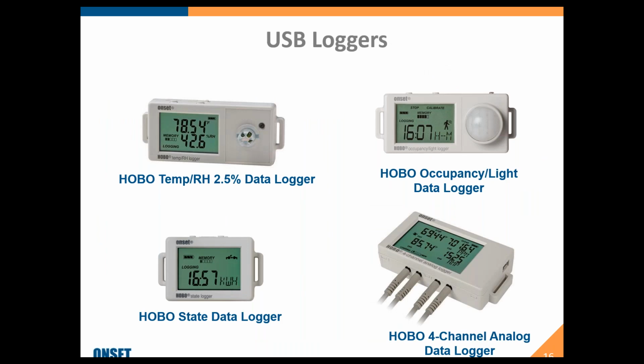So just be aware of that, and we'll go over a few of those. The different types of loggers that we have, I'll start with the USB. So temperature, relative humidity, occupancy, light, on-off state, like I was saying, that may be an open and door close, or an external channel on our UX90 state logger that will take in kilowatt hours, a pulse from a kilowatt hour transducer.